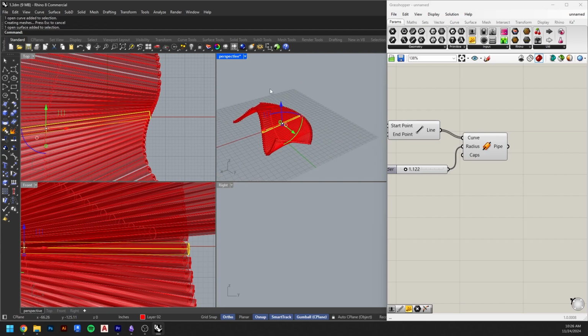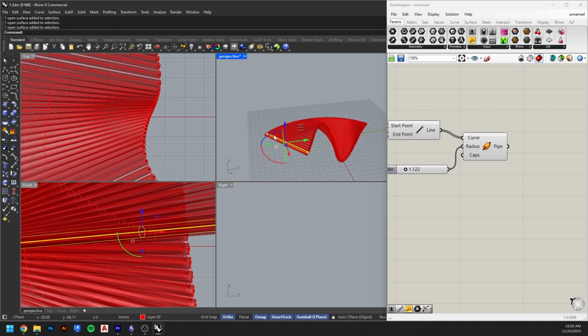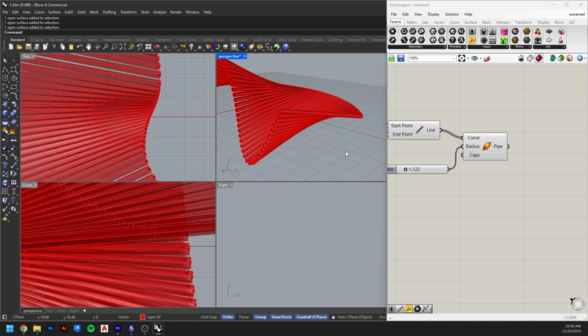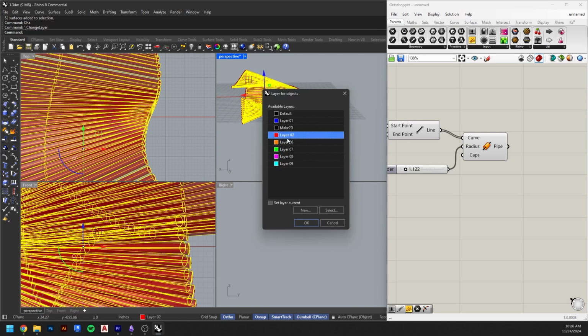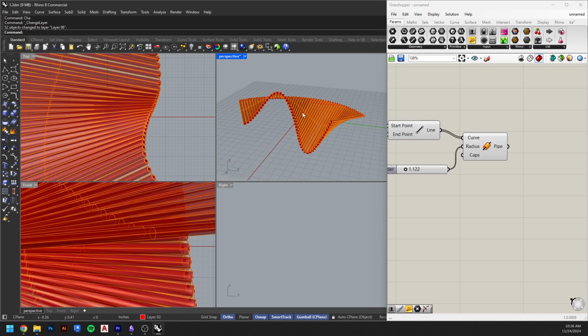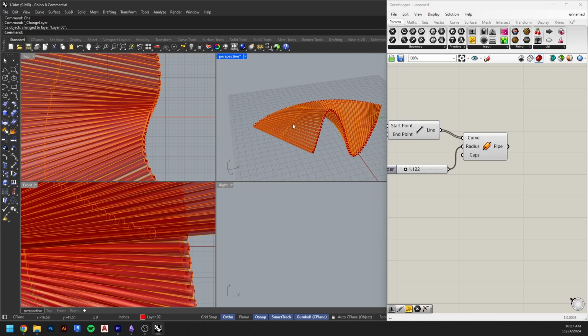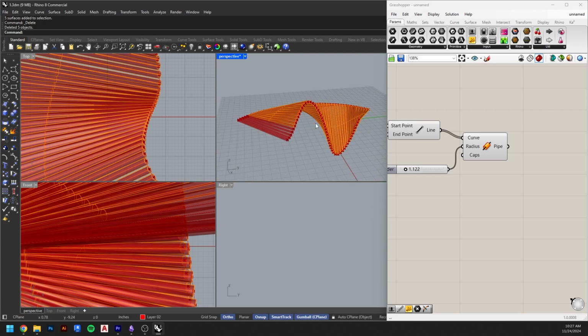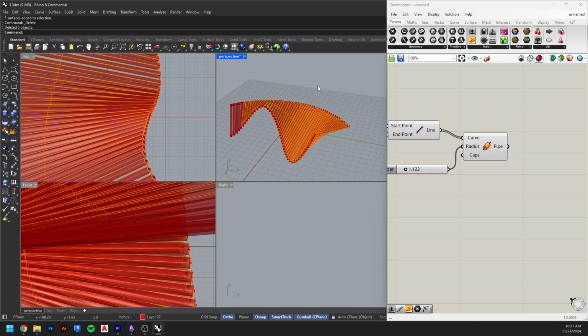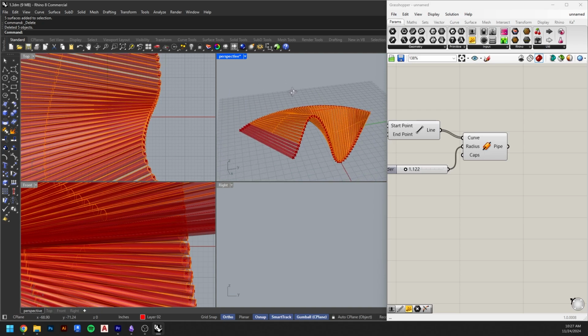And look at that. They have now turned into Rhino objects. Oh, and now I can render it. Now I can cut a section of it. Right now I can group it. And actually, it's a little confusing that it put them all on a red layer. But indeed, that's how this works. And actually, the ghosts are still there. Like, the ghosts are still showing, right? I just deleted those. But I want you to understand that everything that happens in Grasshopper is not real. It's just this ghost, what would happen if you made these changes. And then at the very, very end, we bake, okay?